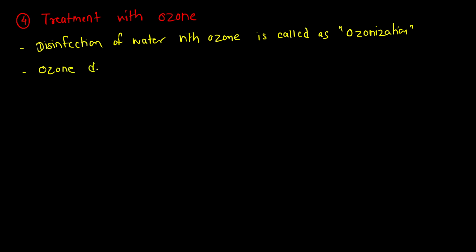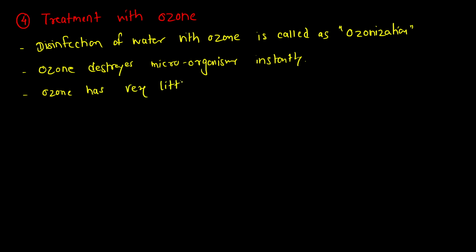Ozone destroys microorganisms instantly. We have seen that KMnO4, the previous chemical, was taking 24 hours to 48 hours to destroy the microorganisms completely. However, ozone destroys them instantly. This ozone has very little residual powers.